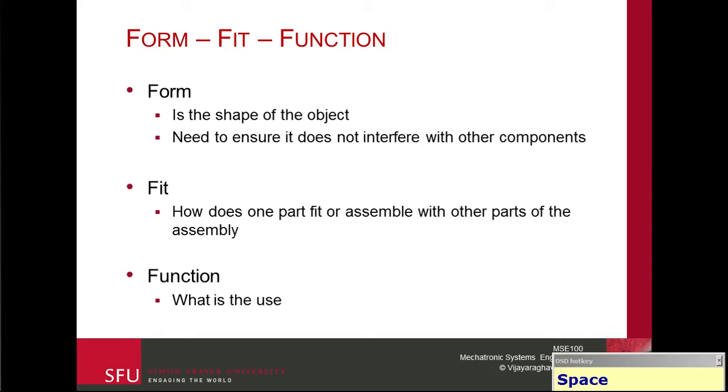This is important because when you document things, everything needs to be in 2D print form. The main thing is, if things go wrong, you need to figure out who's to blame. That's the fun part. If you have a standardized drawing and a missing dimension, then you go back to the manufacturer of the part. This is mainly useful when you're outsourcing the part. If you have all the dimensions in place and there is a mistake, you can trace back through the paper trail and figure out whose mistake it is and who's going to be liable, whose headache it's going to be. So it's important we learn our language correctly so that we don't miscommunicate any information.